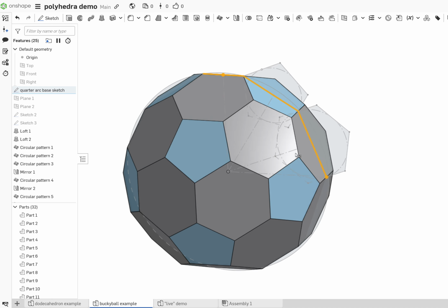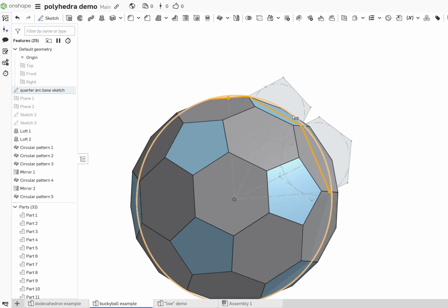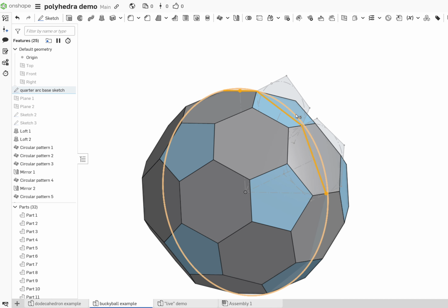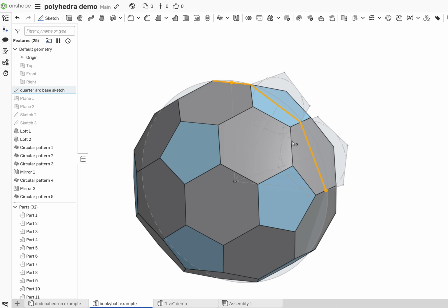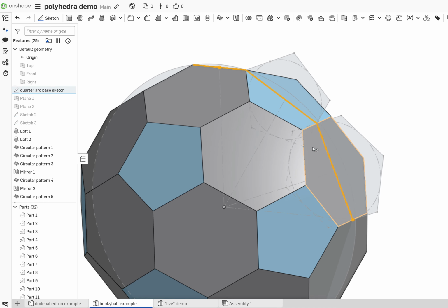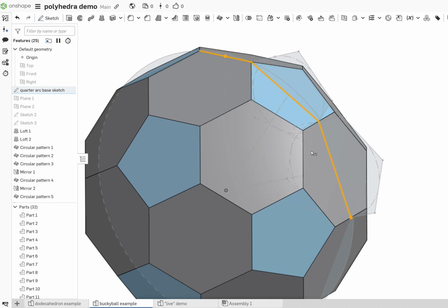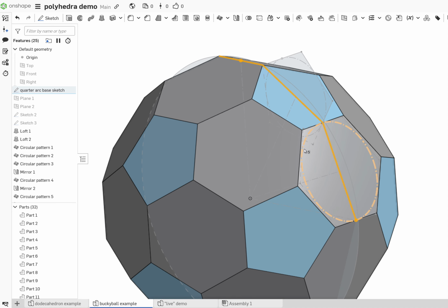And from that, as long as we can make our sketch geometry play nicely, and we know that this pentagonal face is normal to, perpendicular to the center point of that pentagon from the inscribed pentagon, as long as we can keep that face normal and perpendicular, all these edges are the same, they're all glued to the same thing, the sketch solver figures out those angles for us, and it just works.